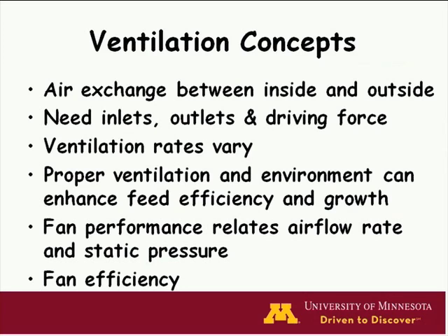So these are some of the key ventilation concepts we want to get across here before we get started: there's air exchange between inside and outside. We need inlets, and we need outlets, and then we need a driving force that's going to cause this ventilation. You'll hear a little bit how the ventilation rates vary for the different animals and different ages, and it's important that we maintain the proper environment with plenty of ventilation to enhance feed efficiency and growth. And then we'll come back and talk about these relationships between airflow rate and static pressure and fan efficiency.